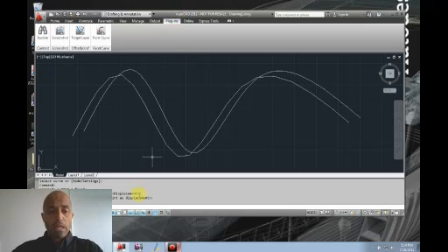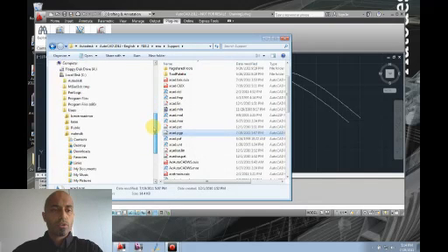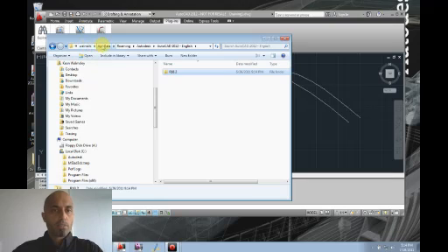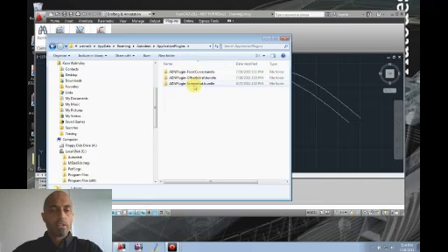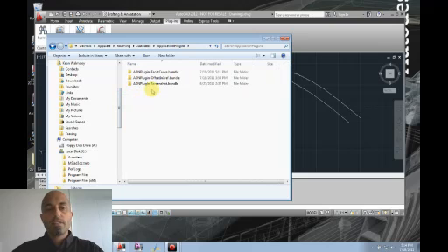Once it's actually installed, there's a few things that you'll find, and if we go across to that same folder, let's go back to App Data, Application Plugins. Now what we find in here is that these are where these applications are installed to, and this is using a technology called the Autoloader in AutoCAD 2012, which looks for plugins in this folder.